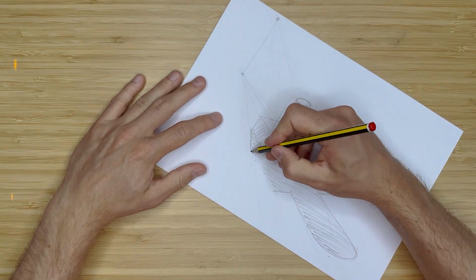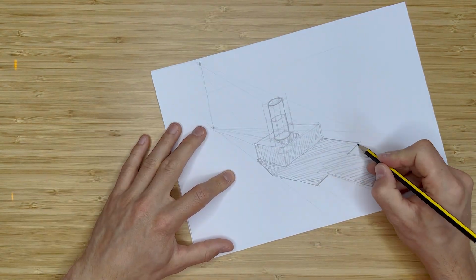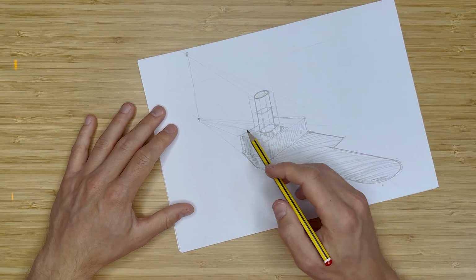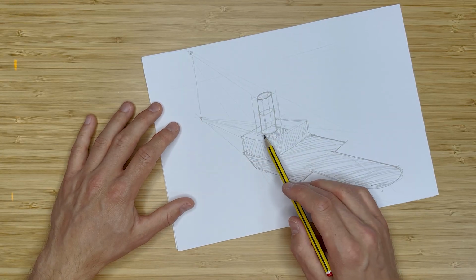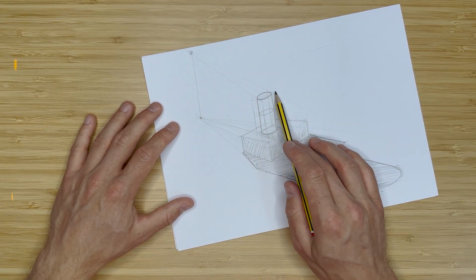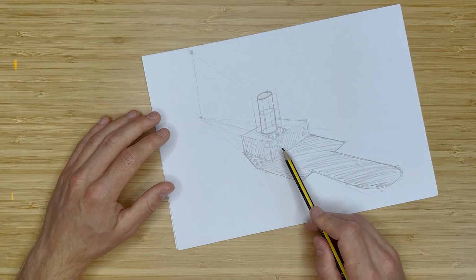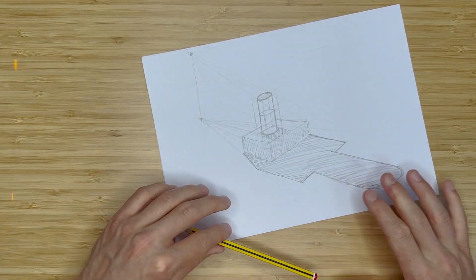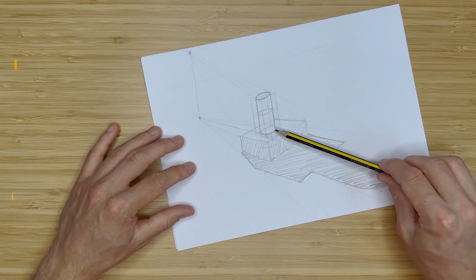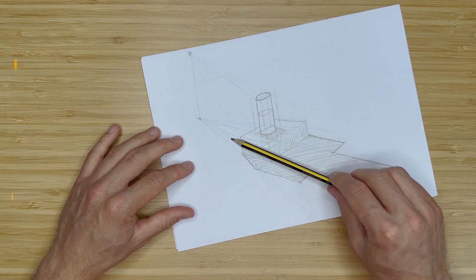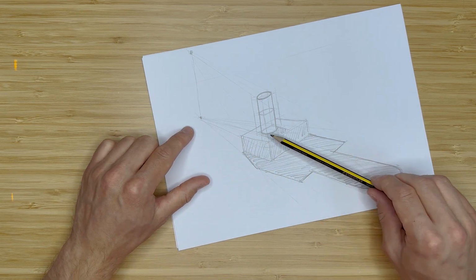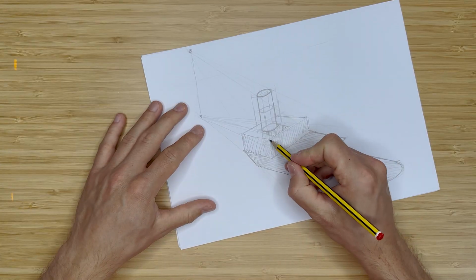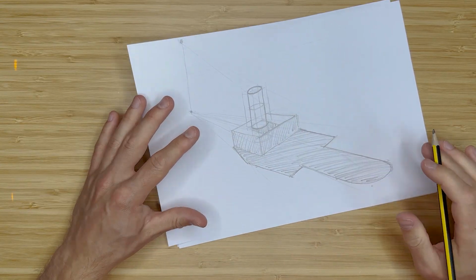Now, if you understand the basic concept, the basic concept being that the point runs through the face, and the top part runs through the top face, you're fine. Obviously, where this was slightly complicated is because this extends down to where the floor is. So imagine this is the floor where the shadow is. We've extended our cylinder and our ellipse down to the floor, and therefore it's come out from that point. If we'd gone through this base part, your shadow would be floating on the top face of this box, which we've got, but it would come out and it would look completely wrong.